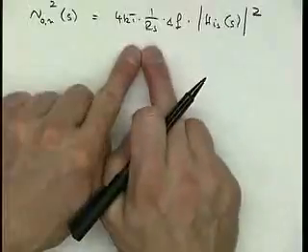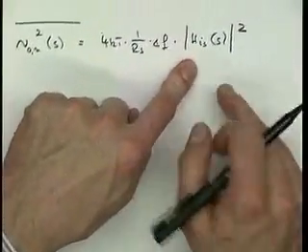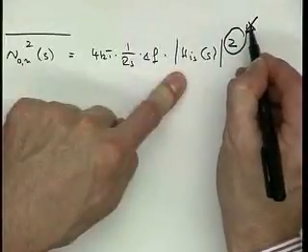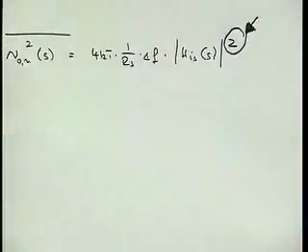Because this is amp squared, we also need to square our transfer function. Very important, right? Before we've said already that noise powers add up, but not RMS values of noise sources.